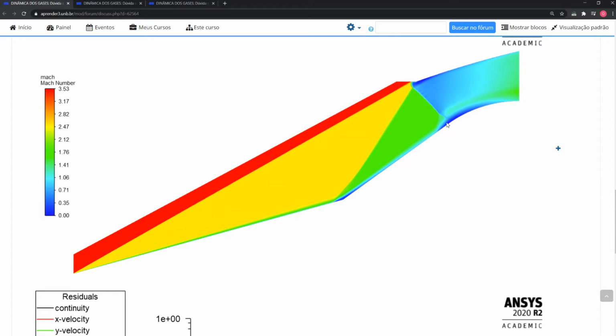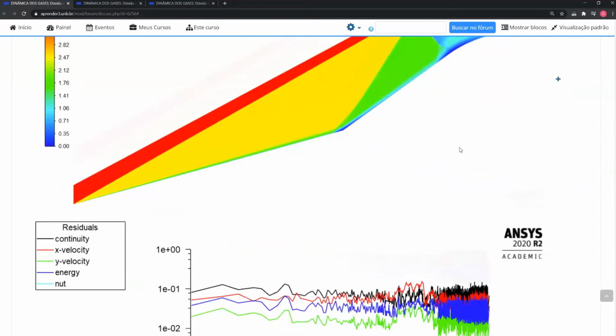So flow has low velocity. Flow is definitely subsonic here in this region and interacts in some way with supersonic flow before the shockwave and subsonic compressible flow after the shockwave. It's usually characterized by very unstable flow behavior, since we also involve the viscous model, and physically this flow cannot converge, not just mathematically, but also physically.